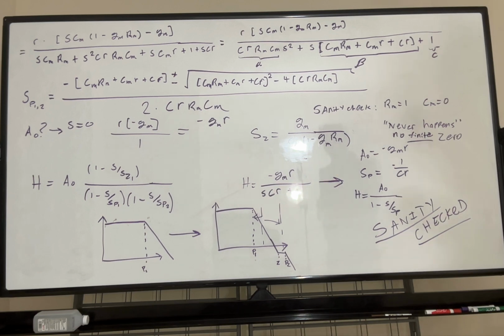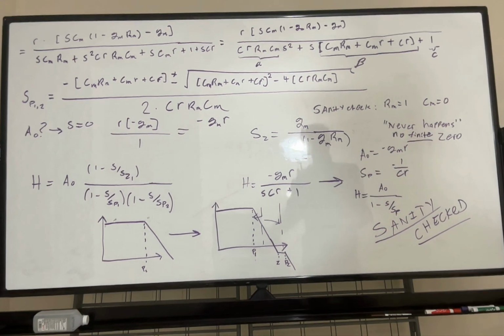I called it CL on the other page, but it doesn't matter. So this would be our transfer function, finally, if there was no Miller compensation. So we now have all the information to make the transfer function for the Miller compensated and the Miller uncompensated common source amplifier. And the pole locations are a little nasty for the Miller compensated one.